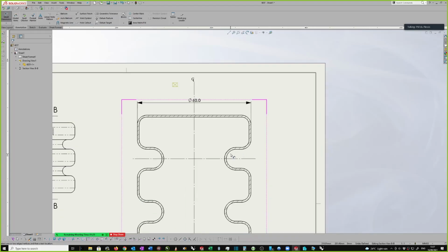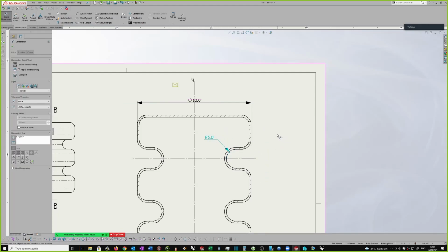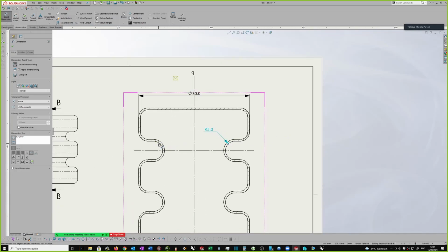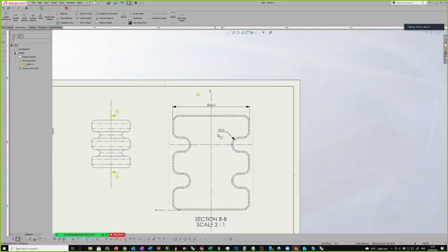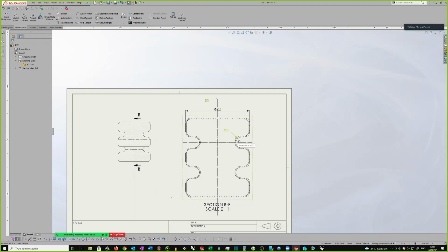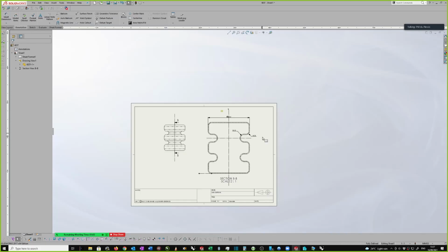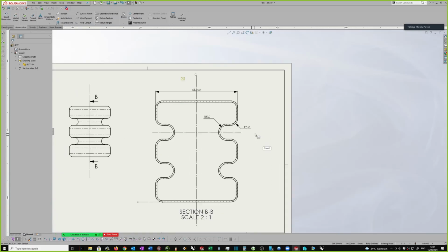Then the other thing is, if you dimension this one here. Oh, someone's alarm's going off. That there, you would not put in another dimension here. That's not okay, because this thing is a round thing. That shape goes all the way around. All of these do the same thing. And you wouldn't put all around because it's obvious it goes all the way around. All right. So yeah, those are the kinds of things that you need to look out for.